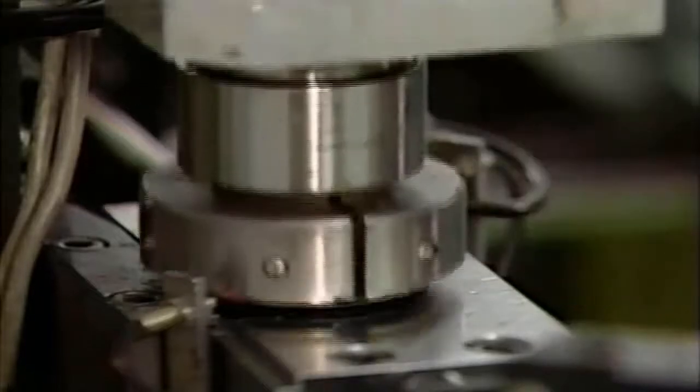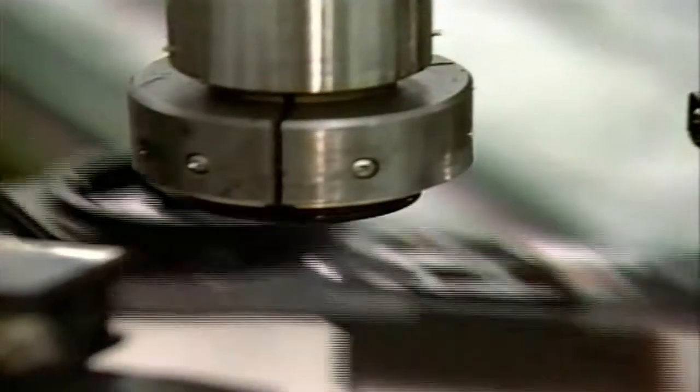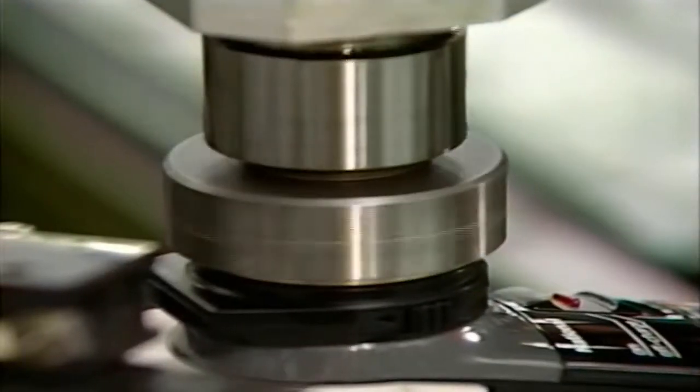In order to overcome this problem, a magnet was inserted. 2 metal plates were also added to the part of the chuck which suffers wear most to prevent malformation. The magnet fixes the position and the plates maintain the chuck walls. The result is accuracy every time and zero stoppages.